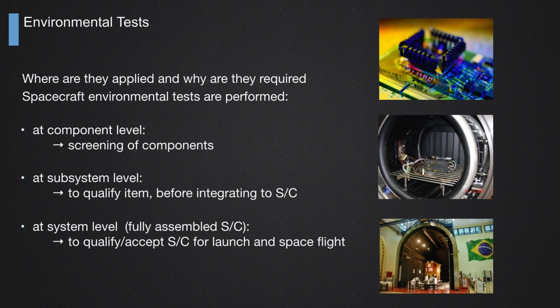When we purchase components from the manufacturer, they come roughly pre-qualified, but after shipping and handling, we have to do some tests with them again, even though they were pre-qualified. Why? Because some of them are qualified but very close to the margin of failure. So by screening the components, we stress them a little bit more. If they are going to fail at the beginning of life, they can fail in the laboratory. If they are very close to failing, they will fail in our laboratory, even though they were pre-qualified.